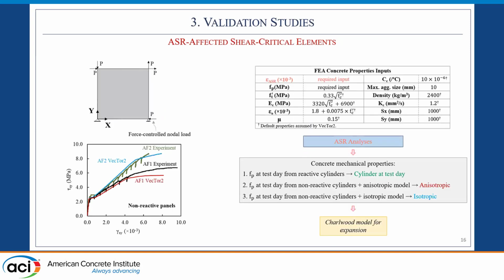In terms of how we model these panels, we used a membrane element, one single element, and we can see on this plot over here the experimentally measured response versus the analytically calculated one. This is for the non-reactive panels. We see a relatively good agreement. What I want you to note here is that for the concrete mechanical properties, we only used the concrete compressive strength, and so no calibration or fine-tuning was done for these analyses.